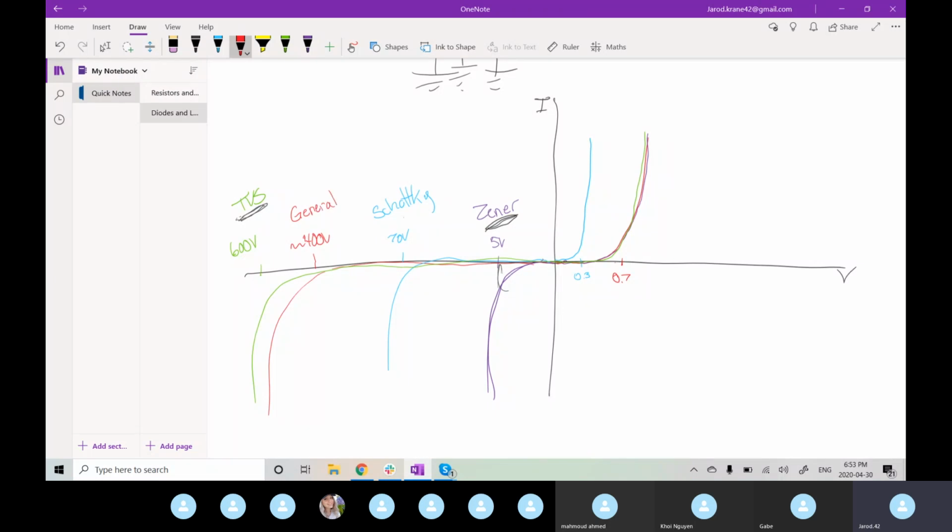They won't happen exactly at their rated breakdown, or their breakdown voltages have a much larger range on them. So when reverse, that's why you would use a TVS as opposed to a general, even though they may break down at the same few hundred. The TVS is going to be more known to actually suppress at that level.